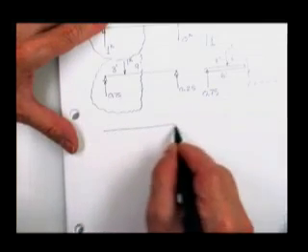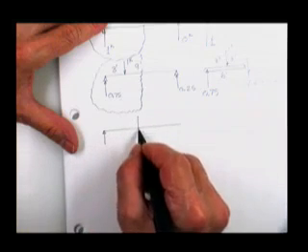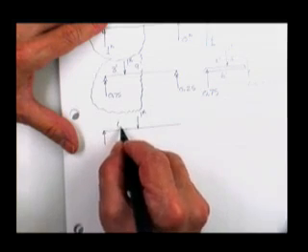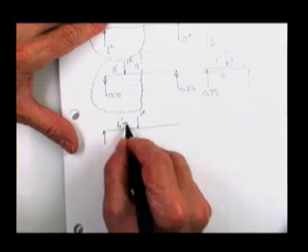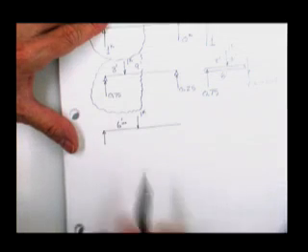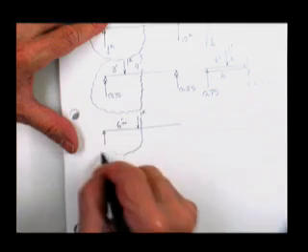Here is the case where I'm going to put the 1 kip load at 6 foot minus, just very barely to the left of the point where you have been asked to solve for the shear.